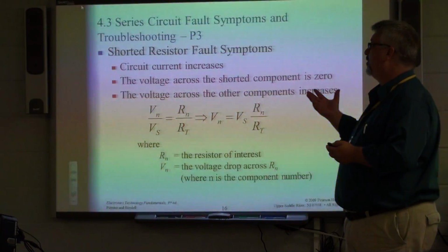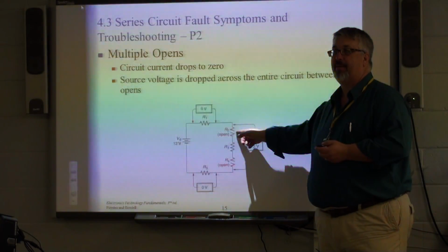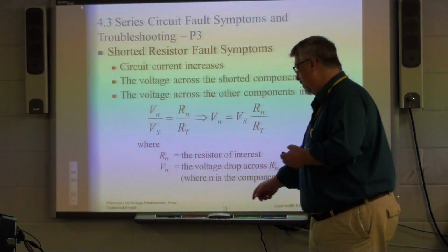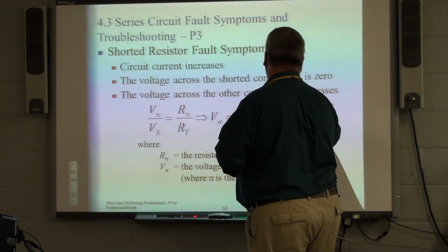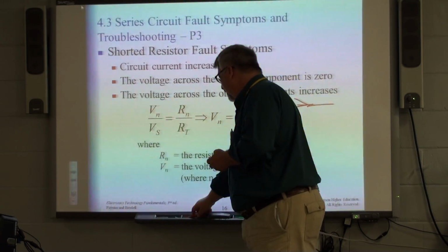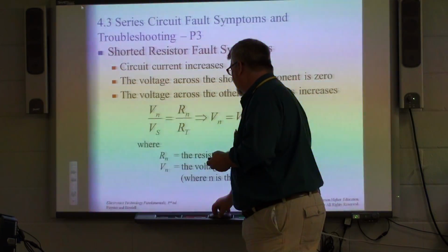So let's say a shorted resistor happens. Now, these are opens, right? They're broken. That's an open. Remember our switch? That's open. This is closed. But when we talk about a resistor missing or a resistor being bypassed, that becomes a short.